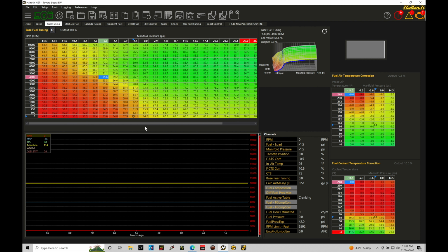We're just going to learn how we program the injector data in this work example, and then we'll go through talking about something known as injector pressure differential, which is something that we definitely want to work with whenever we have a fuel pressure sensor added to our fuel system. I would recommend, regardless if you're naturally aspirated or turbocharged or supercharged, to add a fuel pressure sensor and integrate that into your fueling calculations, as I'm going to outline here in this tutorial. The cost of a fuel pressure sensor is relatively low, but adding the fuel pressure sensor and calculating our injector pressure differential channel makes our fueling calculations improved.